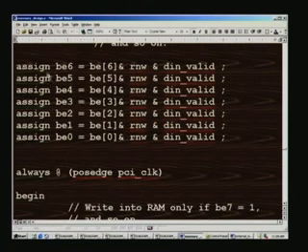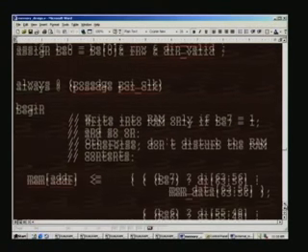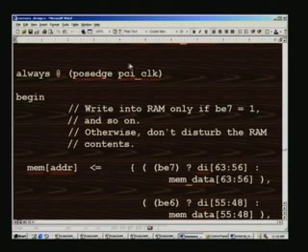So any last minute changes can be very readily incorporated in Verilog that way, and the same is the case for other Bs here, except that different byte enables are selected for that. In order to write, we need to look at the positive edge of the PCI clock. As I mentioned, if it is PCI-X bus it will be 100 megahertz, other PCI buses will operate at 66 megahertz or 33 megahertz, and it can be 32 bit or 64 bit, and PCI-X comes I think in 64 bits.